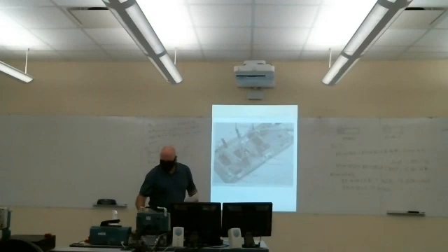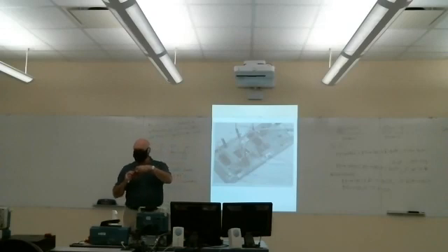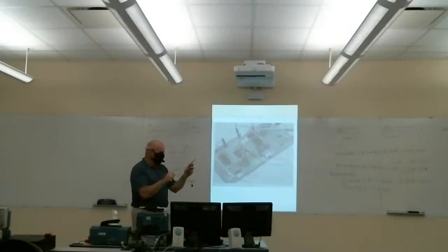So, and you can see on your board, there are these 4 10-pin connectors on the sides here. I think they're labeled J1 through J4. You can access them either through the pins on the top, or they've got connectors on the bottom that you can just insert wires into. And these are all tied, and if your eyes are much better than mine, you can read which particular port pins on the microcontroller these are tied to.